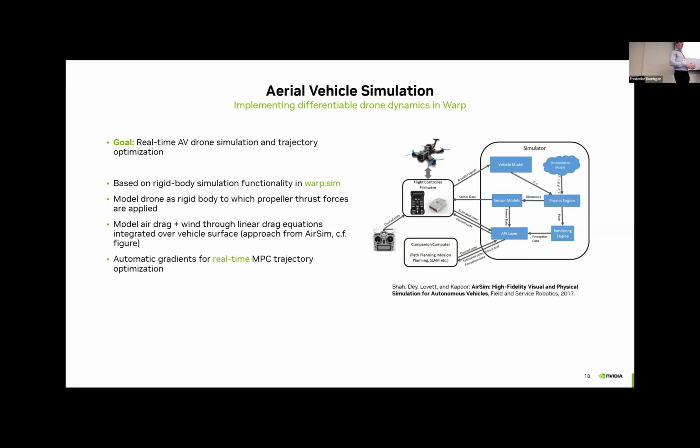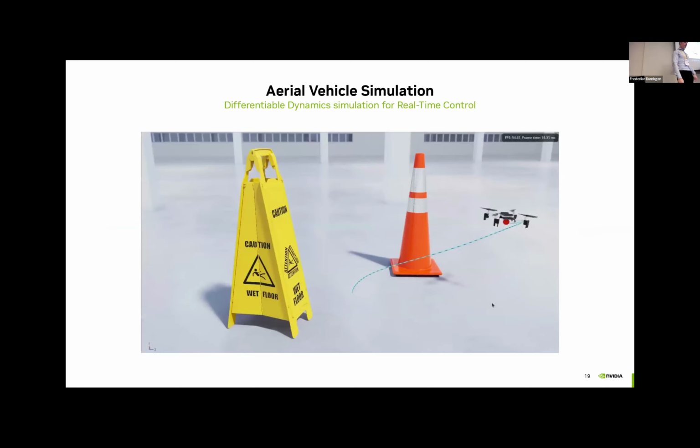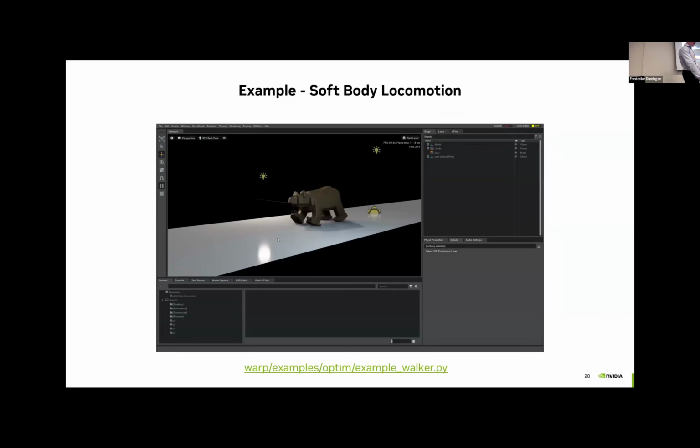And since it's so fast, we can do MPC. So we run the full simulation online in real time, and then can solve to reach certain waypoints really easily, and also account for obstacles, just by adding this to the cost function. And we can do this also in parallel, similar to the sampling-based MPC, where you can make sure you find really good solutions by parallel rollouts, and you still get gradients for those. So you can combine sampling and gradient-based MPC.